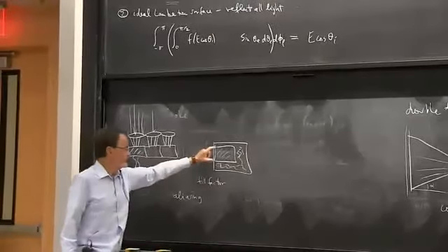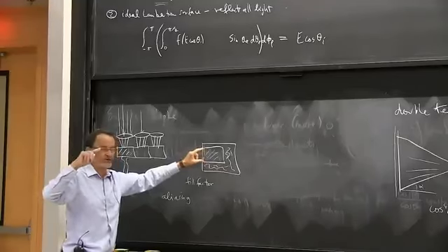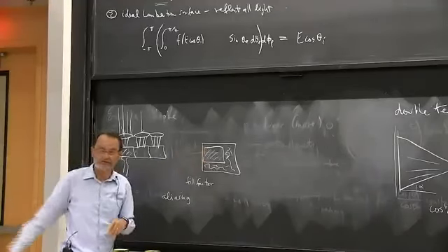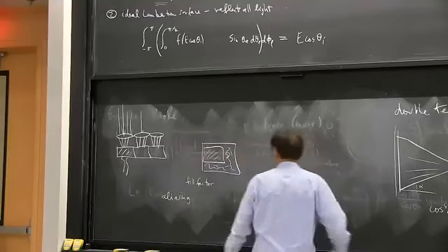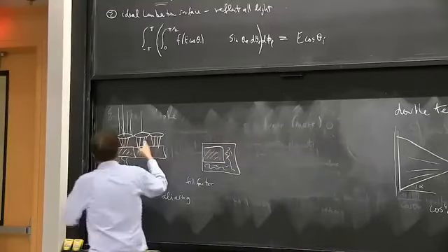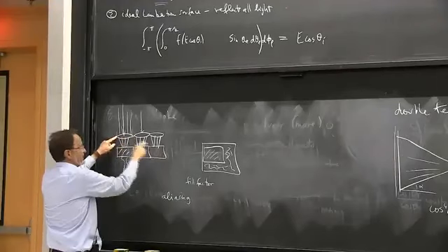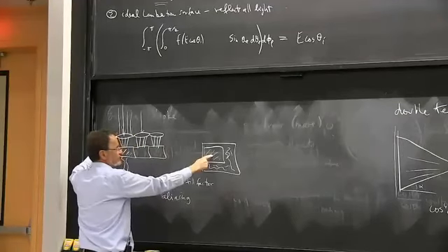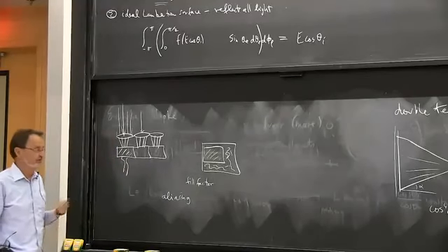But if we have these smaller areas, it's more like point sampling. It's more like we didn't low-pass filter, we're just sampling, and that has very bad aliasing effects. So by using this lens array, we're actually using the light from that whole area and measuring it because we're projecting it onto the sensitive area, and so we reduce the aliasing problem.